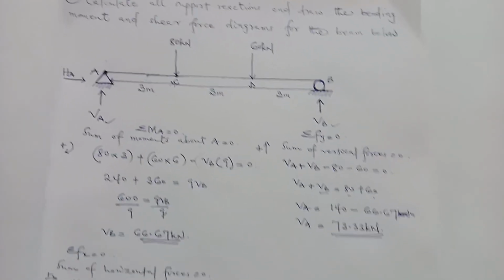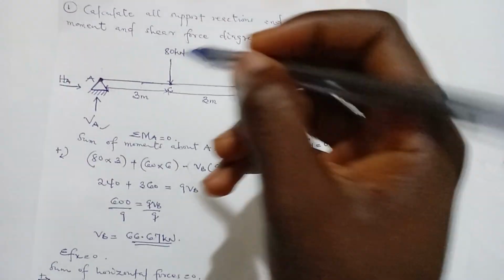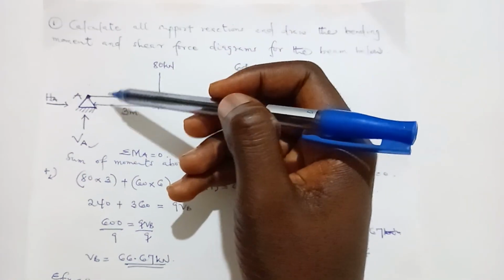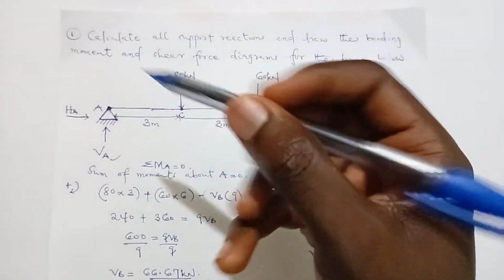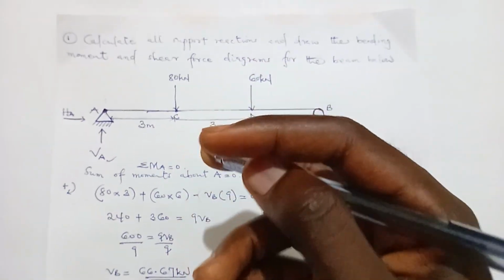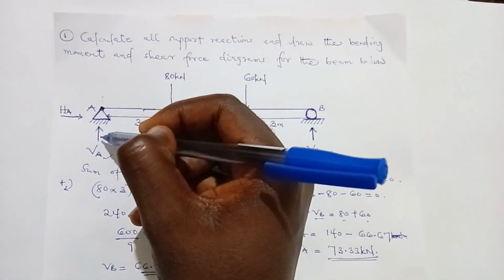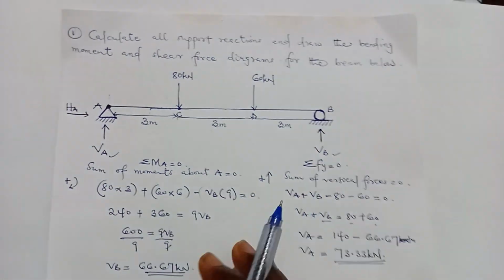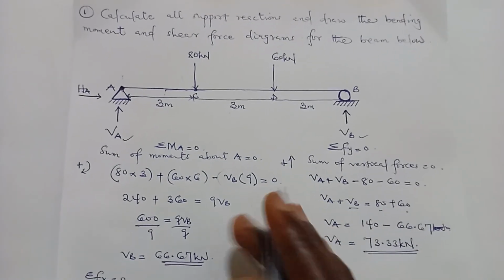Shear force is the sum of the vertical forces acting at a particular point. So when I section the beam, or cut the beam at point A, I have to sum the vertical forces at point A to get the shear force at point A. When you make a cut at A, you choose to take either your left or your right. But this trick helps me in calculating the shear force, and I'd like to share it here.